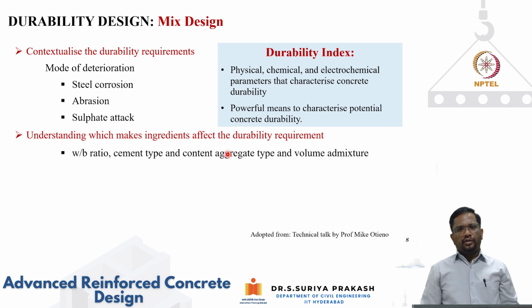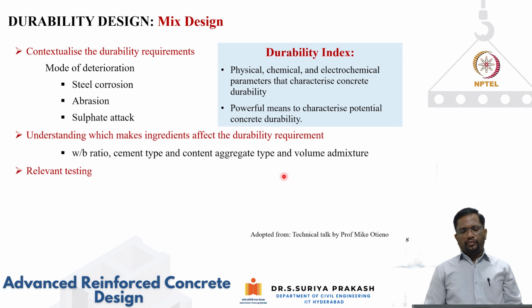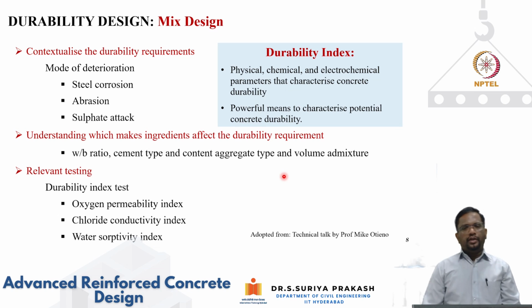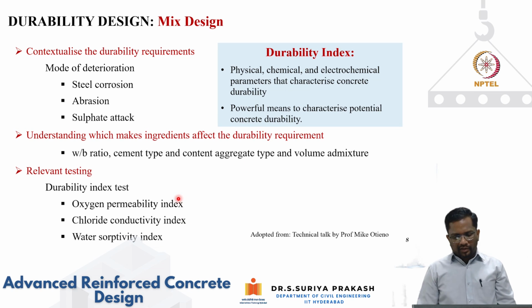If you have abrasion or erosion kind of issues, we know that we need to use hard, good quality aggregate with a very good bond between aggregate and cement paste. Similarly, the kind of admixture that we use and relevant testing. Usually these are the three common tests that are recommended.